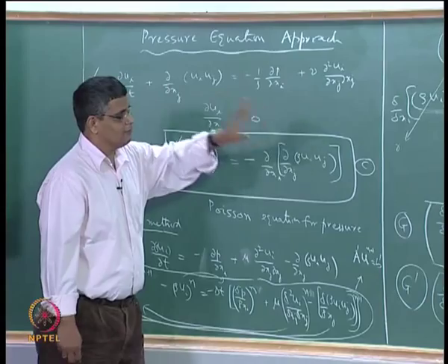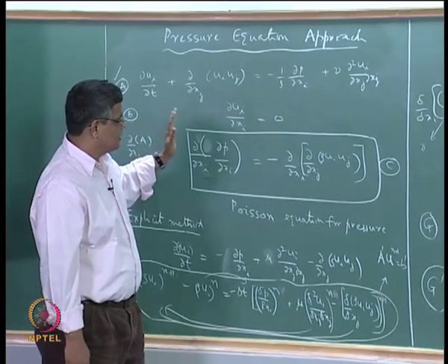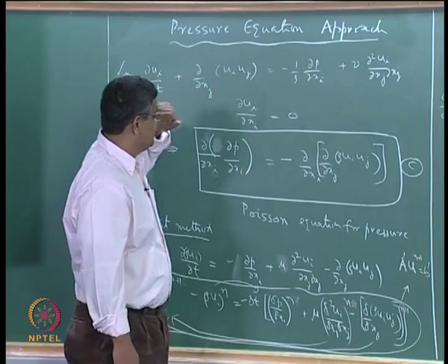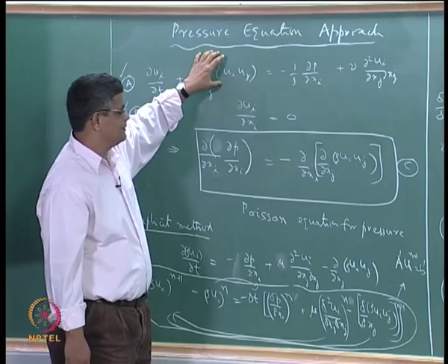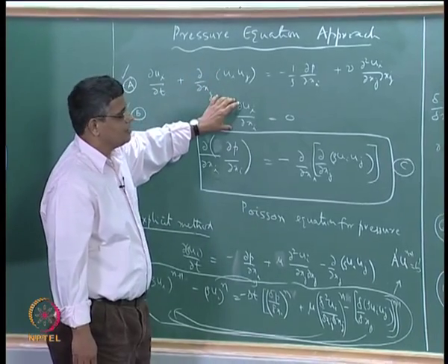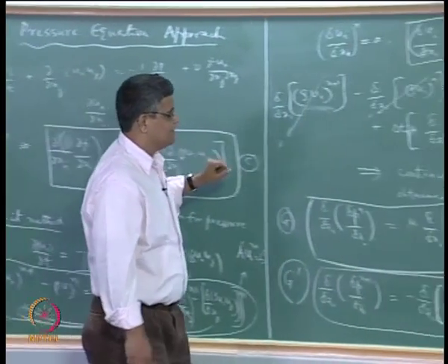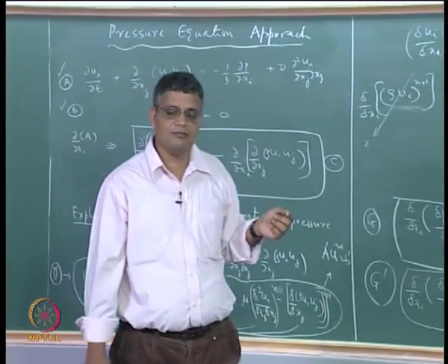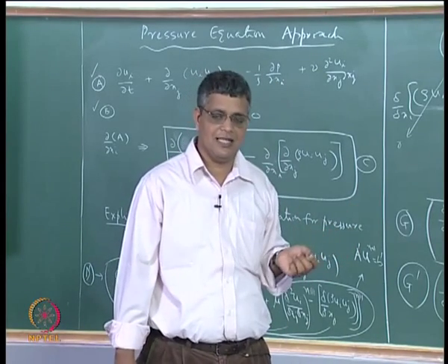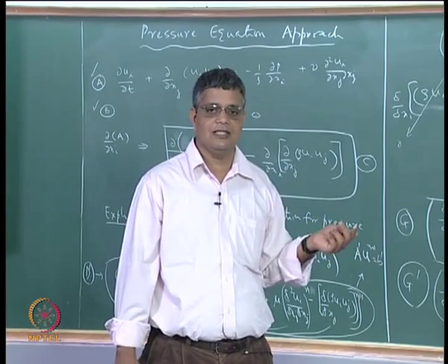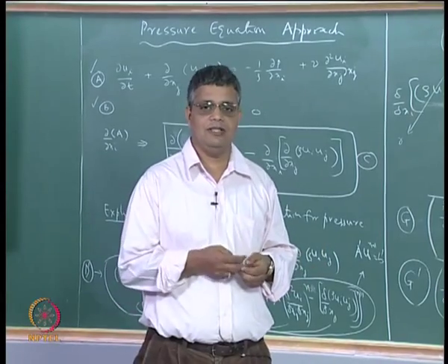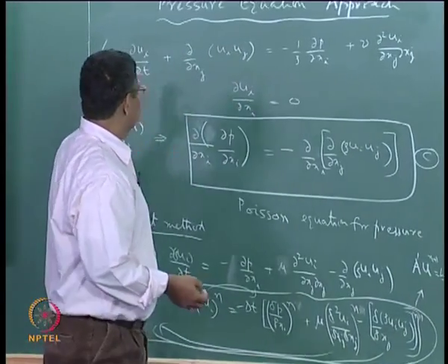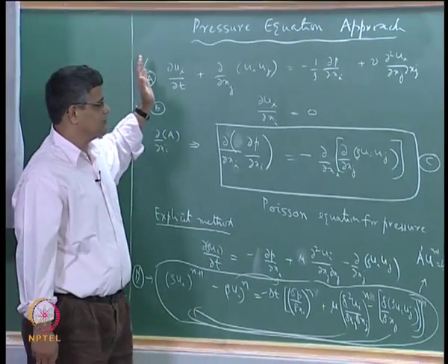So this overall pressure equation method is solving the momentum equation like this, and the continuity equation is being used in deriving a pressure equation, okay, a pressure which will enable the velocity at n plus 1th time step to be satisfied with the known values of u and p. Okay, so that's the pressure equation method. It can be applied for time accurate solution of UVPW.